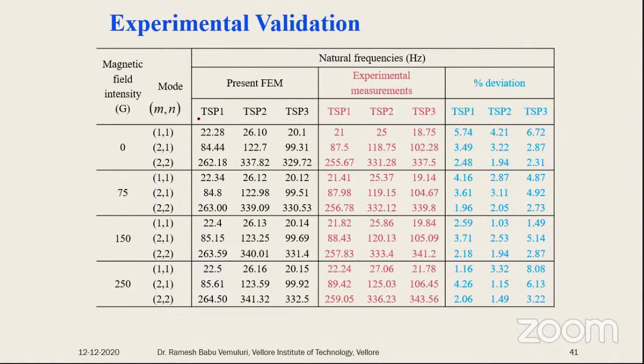Here again we did an analytical formulation using these composite and energy formulations, then applied the finite element method. Here it took a 4-noded rectangular element, with 4 nodes and various shape functions, and after these shape functions we converted these energy equations into the form of the FEM.